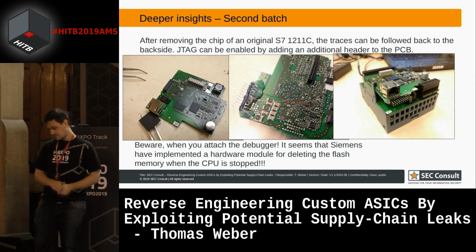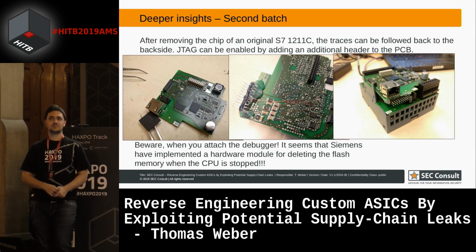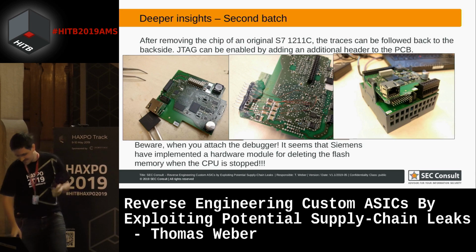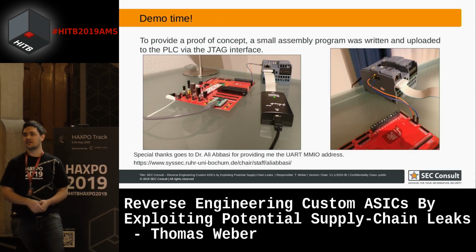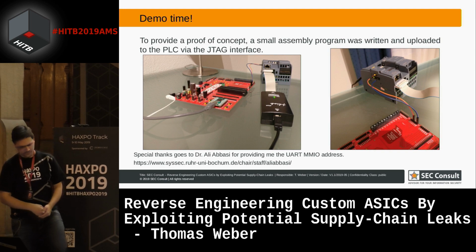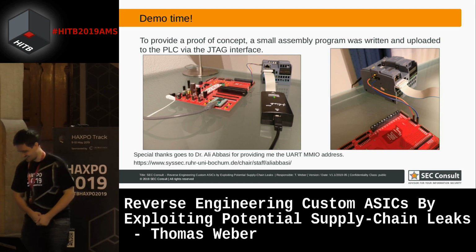When you stop the CPU, a watchdog runs on an internal hardware module embedded in the system on chip. When you leave it stopped too long, it clears the whole firmware from the device. That was not nice, but at least you can program it again. I saw that after attaching to it and reading and writing some values. So I broke three of the devices.